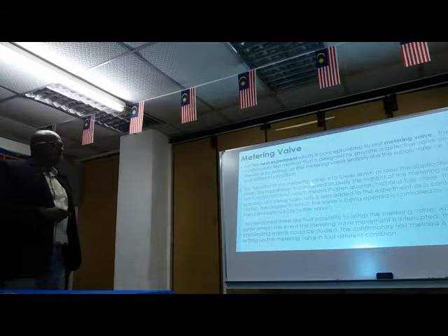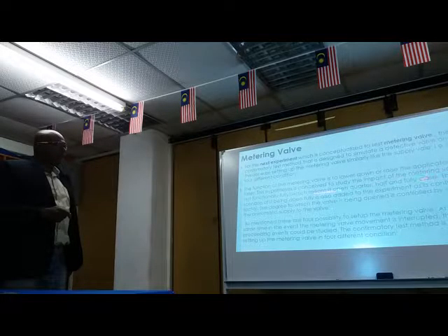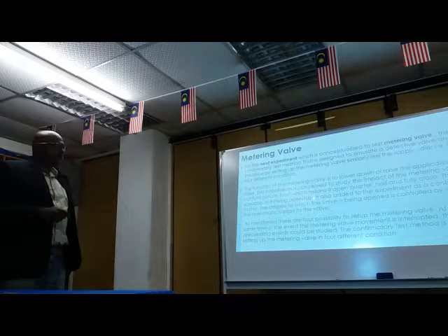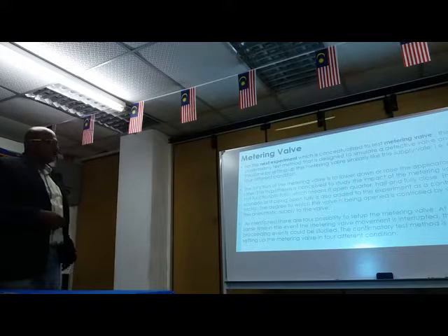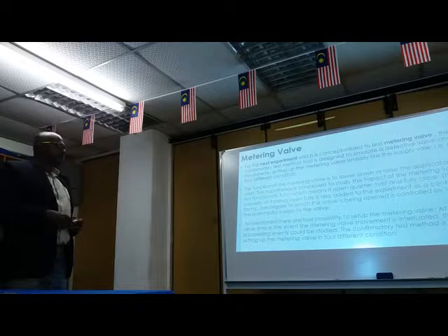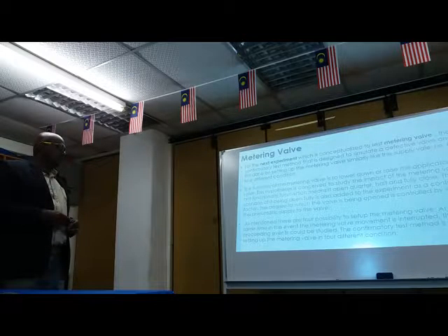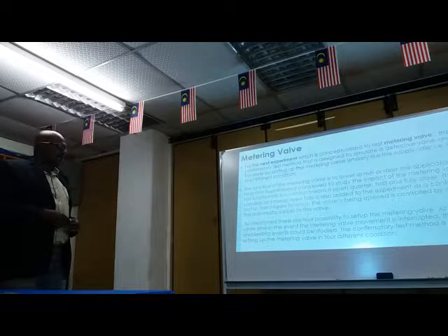The function of the metering valve is to lower down or raise the applicator roller. This hypothesis is conceived to study the impact of the metering valve not functioning fully, which means it is open quarter, half, and fully closed. The scenario of it being fully open is also added to the experiment as a control factor. The degree to which the valve is opened is controlled by varying the pneumatic supply to the valve. As mentioned, there are 4 possibilities to set up the metering valve. At the same time, in the event the metering valve movement is interrupted, the preceding events will be studied.